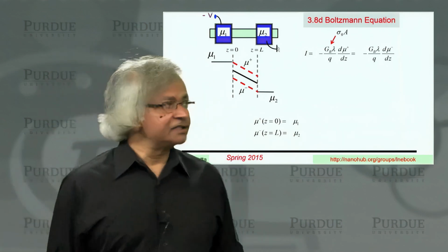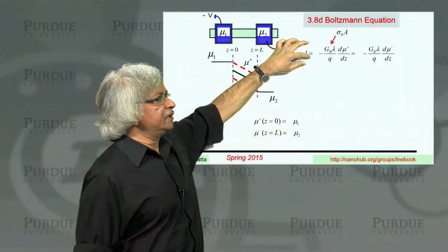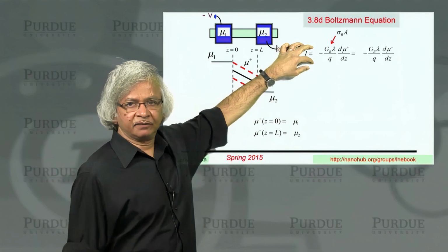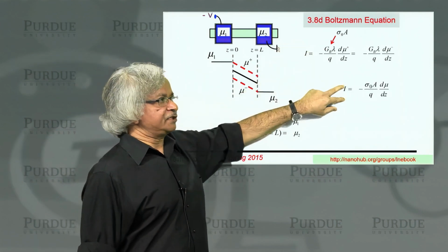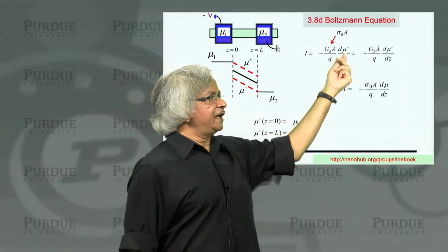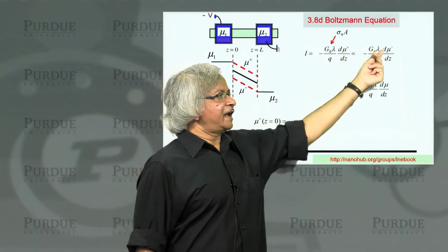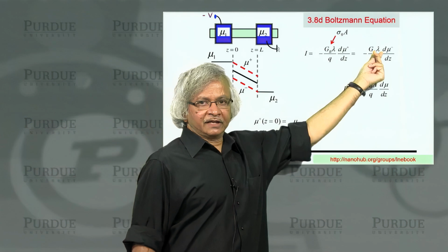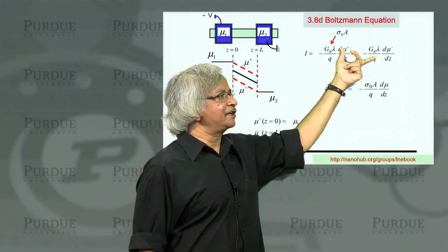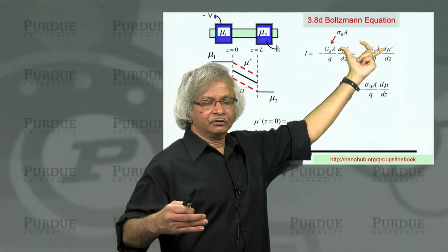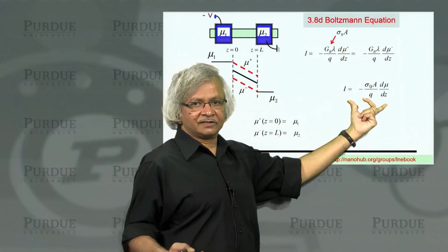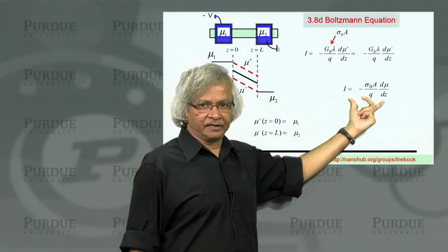On the other hand, you could say that let's not bring in these two equations for two quasi-Fermi levels. Rather, let's just use an average, because I could take this equation and add to it that equation and get a single equation for the average potential, mu plus plus mu minus divided by 2, and it would look exactly the same. So that's the normal diffusion equation, right?